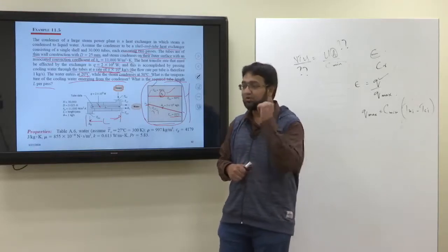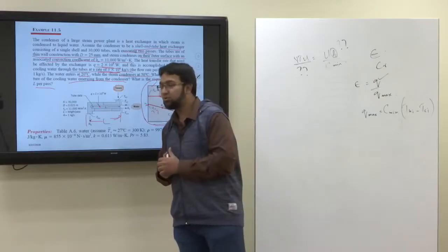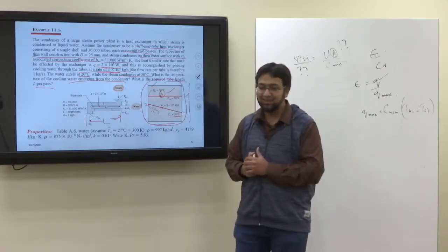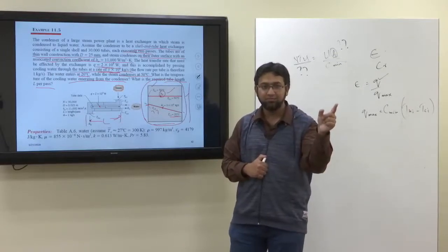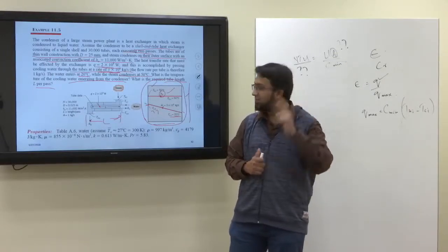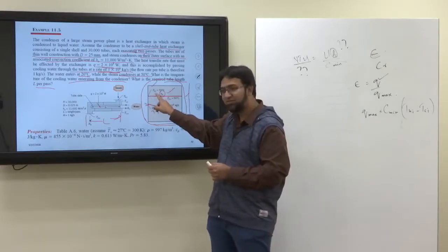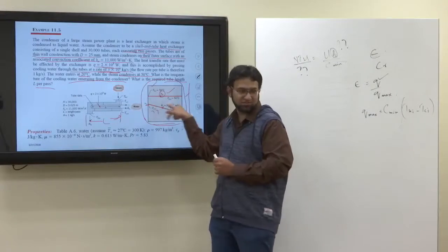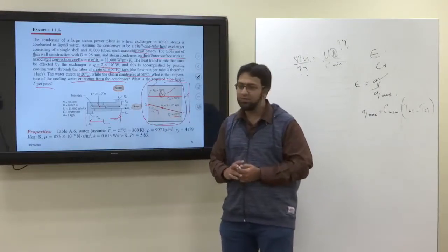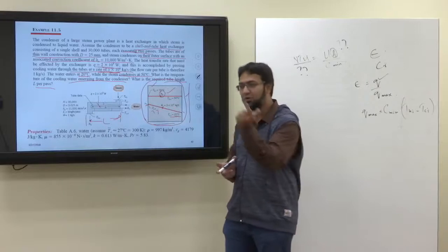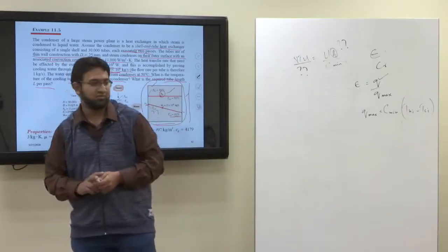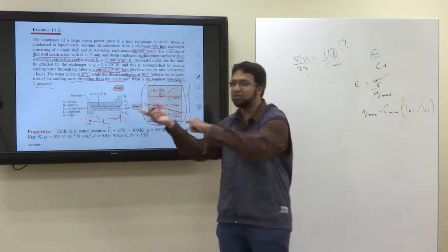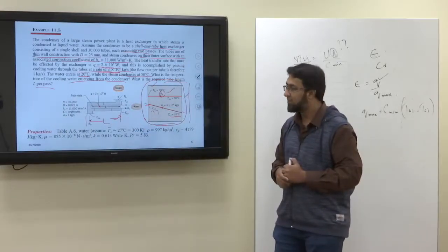Okay, that's good. But there is one thing, as I told you, that C for the case of evaporation or condensation goes to infinity. So for this case, C is infinity. So already the minimum case is the other case. That's what we know. If it is condensation or evaporation, C for that case is infinity. So C minimum becomes the other case, right? So we can use that.